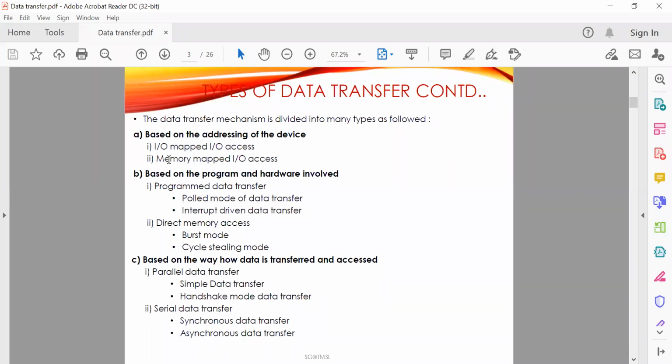Next method, which is the serial data transfer method, where there are two techniques. Now, before going to discuss these two techniques, I would like to share something, that is parallel data transfer. It has some drawbacks. And what is the drawback? It needs several wires to transfer all the bits of data, so it cannot be used effectively for long distance data transfer. As one wire is used for each bit, byte wise data transfer is 8 times more expensive than a single bit transfer.